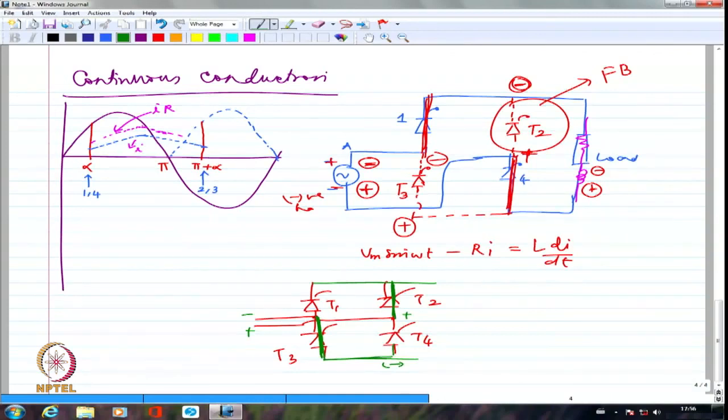The supply voltage is the one which is coming across those two devices to turn them off. So this line voltage which helps the commutation or turning off of the thyristor is known as line commutation or natural commutation. The other one we discussed earlier with the LC circuit and diode and so on, that was forced. We told the circuit that according to this design, you are going to have a reverse voltage at this point in time. Here we don't have a control, it is at 50 hertz.